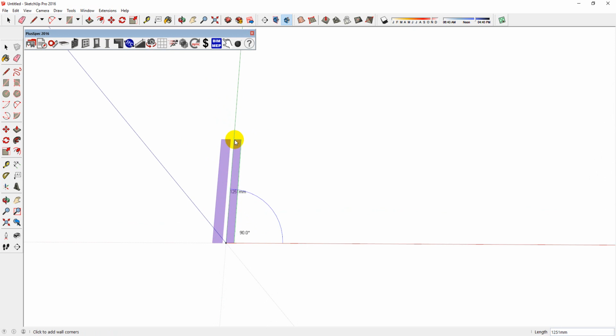You can see that the wall alignment has been set to the inside edge of the interior wall, and you can see it with that little crosshatch. To toggle through your wall alignments, click on the right arrow key on your keyboard. And this will go through the various alignments, the inside, the center points, and the exterior.